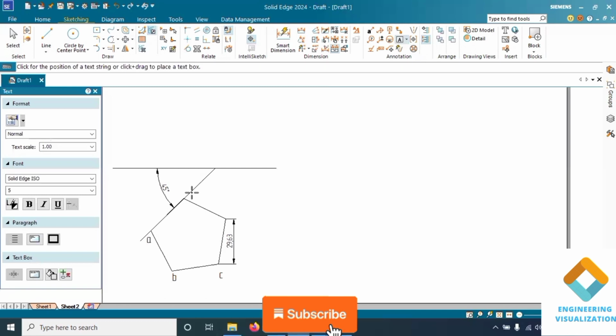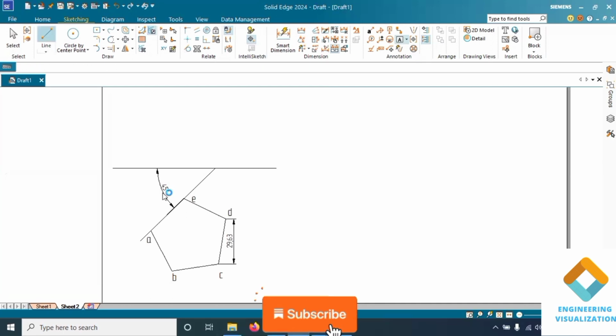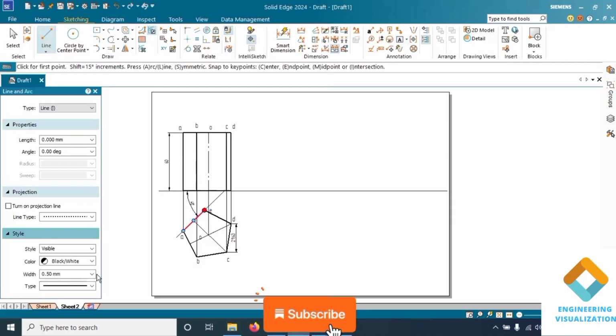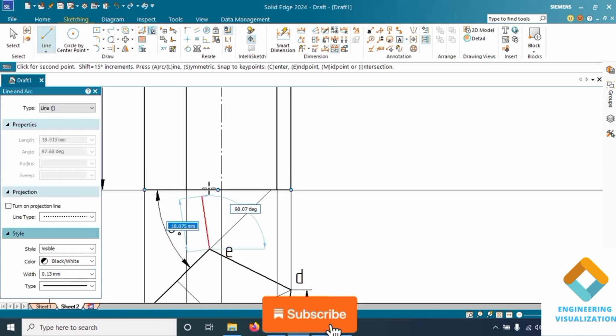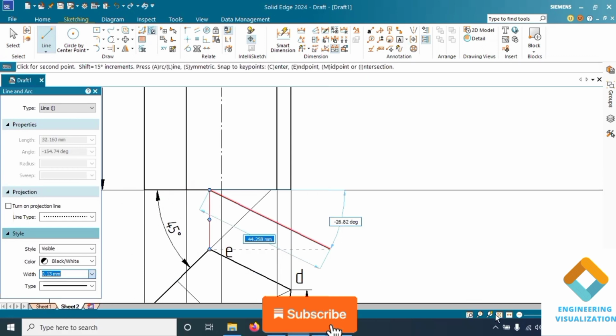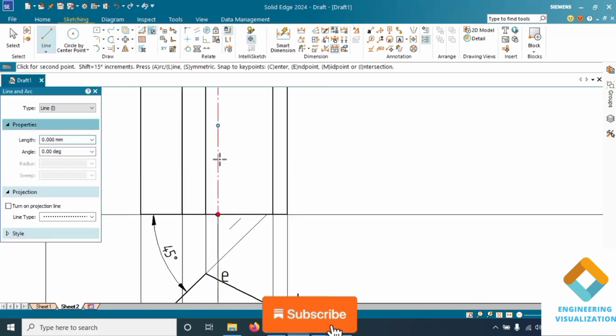After giving the namings, we need to draw at least two or three perpendicular bisectors to get the center point. So after drawing the front view, we need to draw the projection line for this end also. Draw a length of 30 mm from the base.